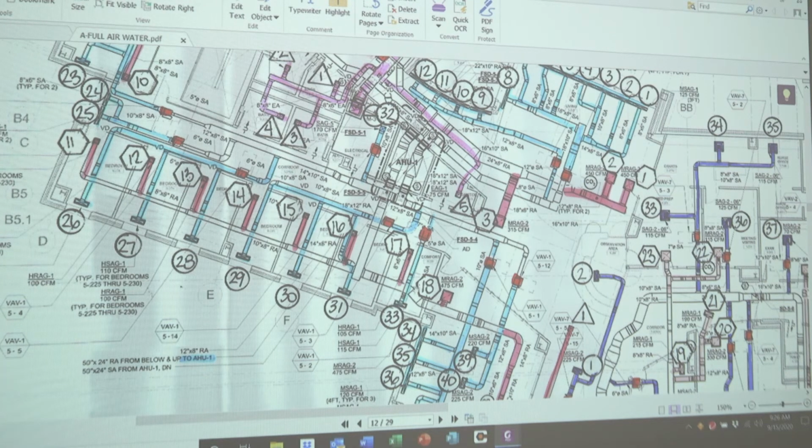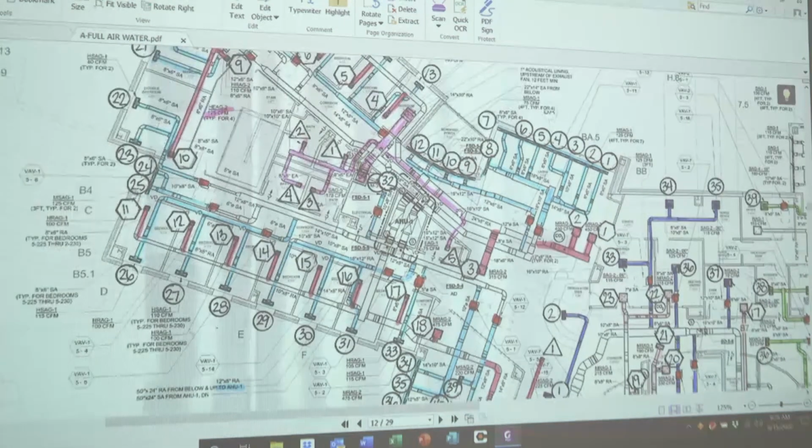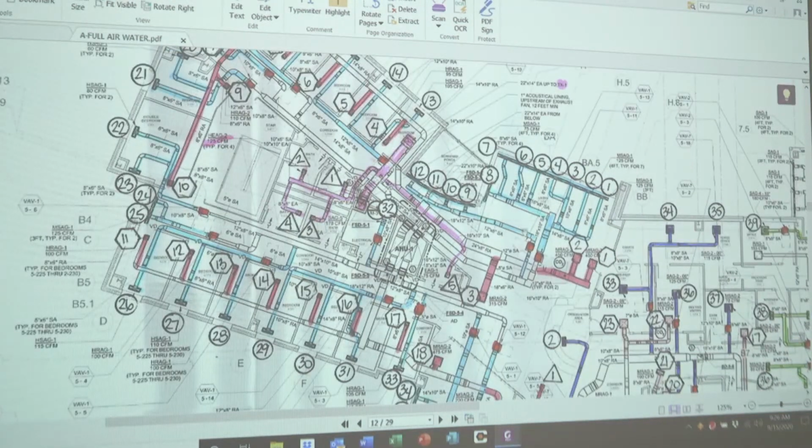As you see here, you have a VAV box, right? This is just serving one comfort room. Your next VAV box is serving 3 bedrooms. Your next VAV box is serving 3 bedrooms. You have a VAV box which is typical that serves the end of each corridor. So you start to see, when you look at the overall layout, we'll be looking at the color blue, turquoise. All of the VAVs associated with air handler unit number 1 are this turquoise color that you're seeing here.